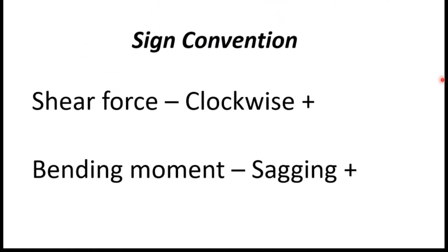First we have to know our sign convention. In this video I am going to use this sign convention, that is, I will consider shear force clockwise positive and bending moment sagging positive.